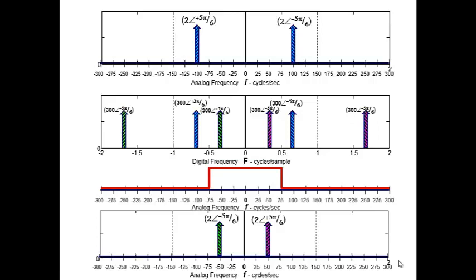We're just using trigonometric identities here. So that's what we alias to. If we were to convert that to a discrete time signal in the digital realm, x sub n, which is aliased, it is minus 4 sine of 2 pi times 50 over 150 n plus pi over 3.